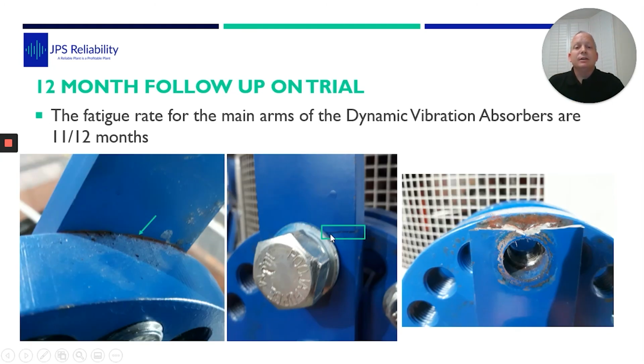If you look here, a little crack, and we can see signs of fretting. Now the motor was still running when we went on site. This one wasn't working, but it stood dead still. Tethers, safety tethers were still there, but nothing was wrong with it. And then in hindsight, you think about it, we designed it to vibrate at a certain frequency. As soon as that bar cracked, the whole dynamics, the physics of that bar changed. So hence, it stopped vibrating. So it literally just stood there. You could grab that and just pull it off. And you can see there, it is cracked exactly where you would expect it to crack.